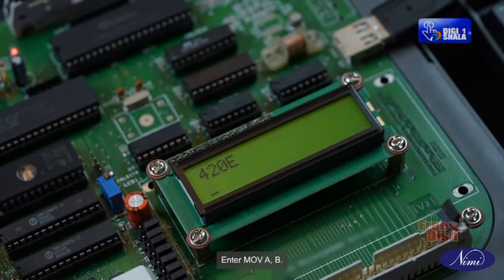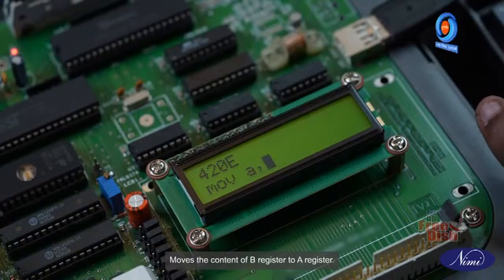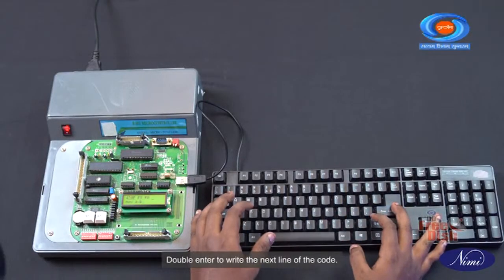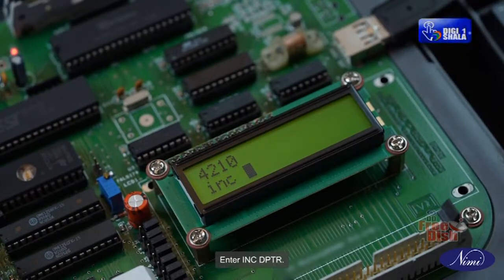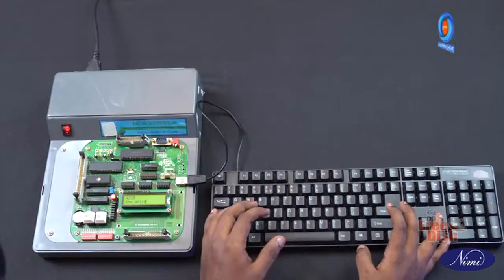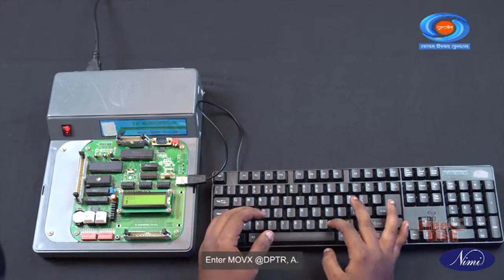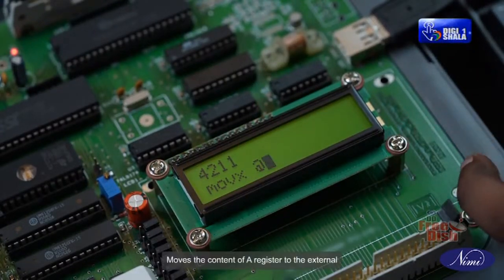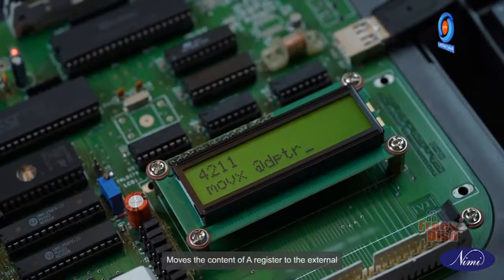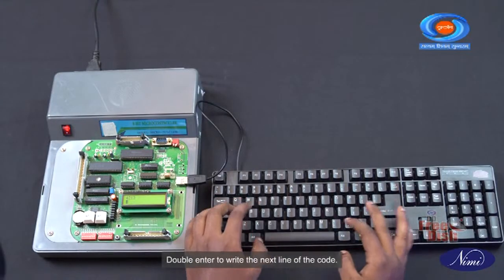Enter MOV A, B. Moves the content of the B register to the A register. Double enter to write the next line of the code. Enter INC DPTR. Increment the DPTR register by 1. Double enter to write the next line of the code. Enter MOVX @DPTR, A. Moves the content of the A register to the external memory address. Double enter to write the next line of the code.